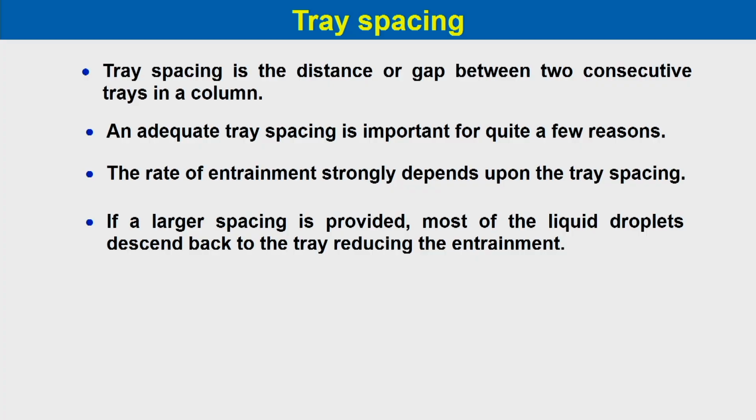Not only that, tray spacing is also important in the case of froth formation and flooding of the column, which greatly reduce the tray efficiency.